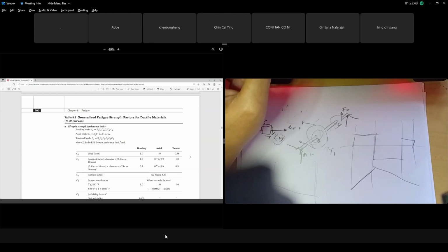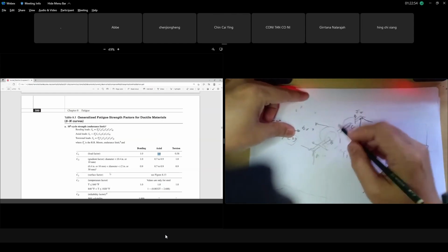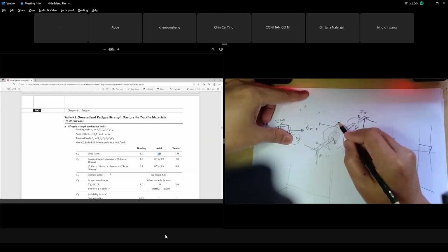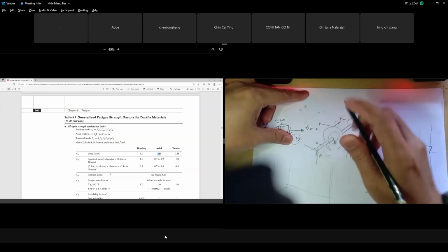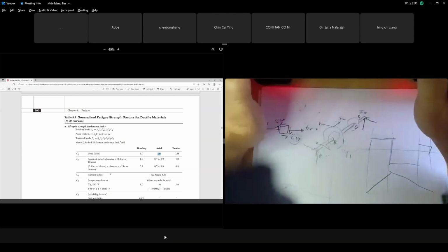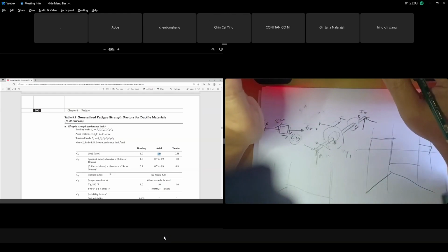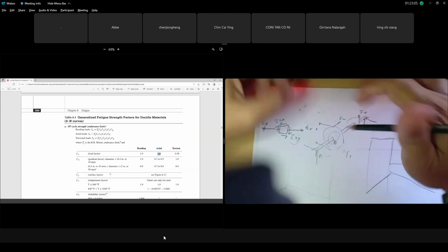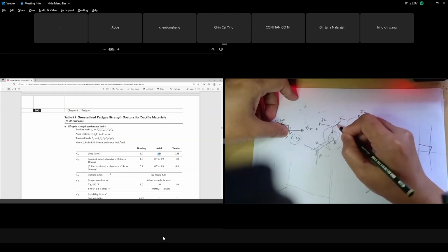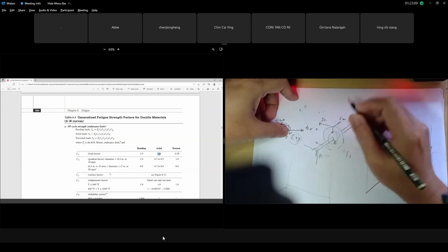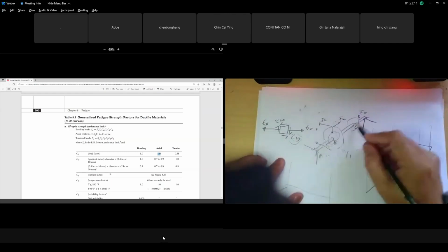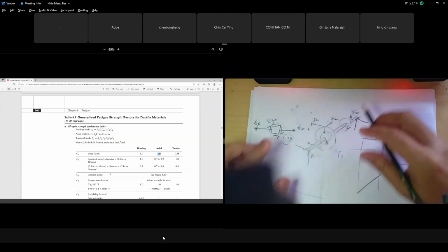Perfect. Okay. Axial, sometimes in exam questions for a shaft, there is a bevel gear. Bevel gear has axial force. You know bevel gear, but we don't learn it. We use spur gear in this course. Bevel gear has three components: we have F tangential, F radial, and F axial. The axial could produce axial stress, but the axial stress is normally low.